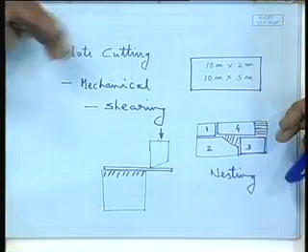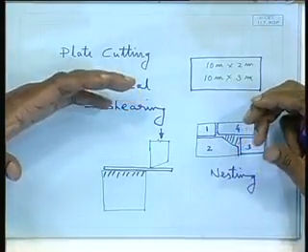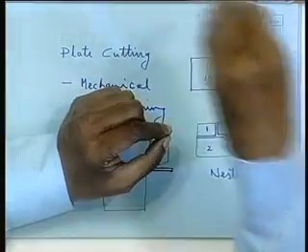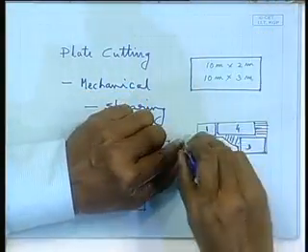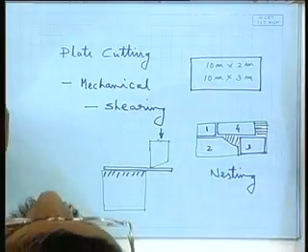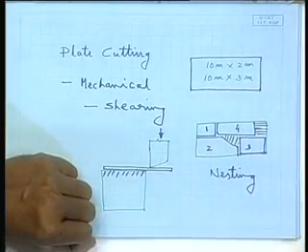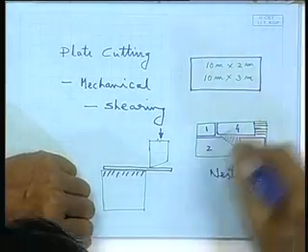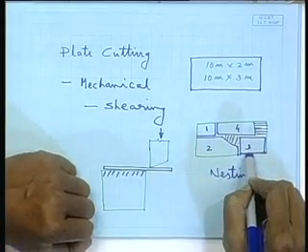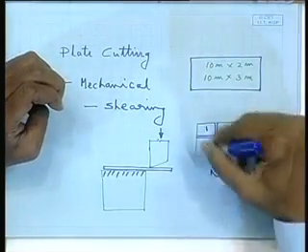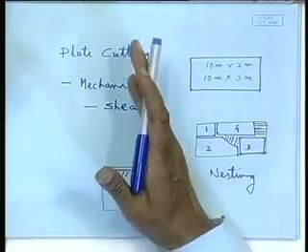Now, once the nesting is done, you need not physically draw this on a plate, because we can have a numerically controlled cutting machine. Once this diagram is known, the computer can drive the cutting tool as per this diagram, so automatically your plate cutting is done. You need not make any drawing as such, but if you do not have a numerical control cutting machine, then obviously there is no other option than to draw this physically, make punch marks and then cut by whatever means.